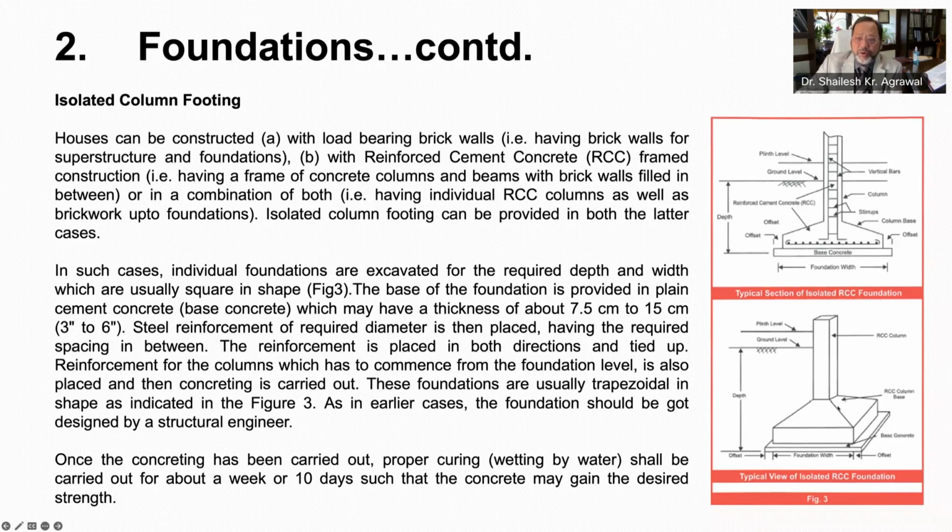The isolated footings are normally trapezoidal in shape to save material. Once the concreting is done, the proper curing is a must and needs to be carried out for at least a week or 10 days so as to get desired strength. It is advisable to seek the foundation design from structural engineer.